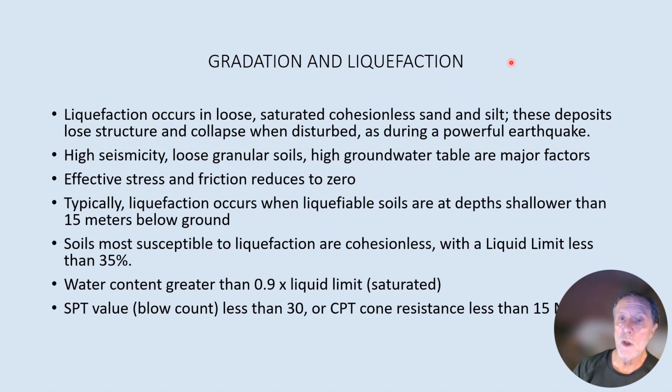Why is that important? Well, gradation, here's one example of why it's important. It relates to liquefaction. And liquefaction, as you know, is the phenomenon when during an earthquake, saturated loose sands can liquefy and lose volume and cause above ground structures to actually settle. So it's important to understand the gradation of the soil, whether it's a granular soil, and it occurs when you have liquefiable soils at depths shallower than 15 meters below ground.